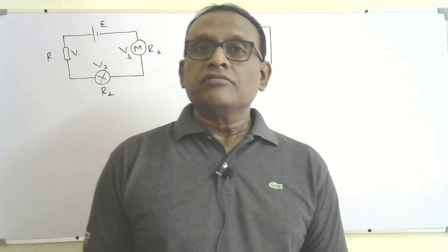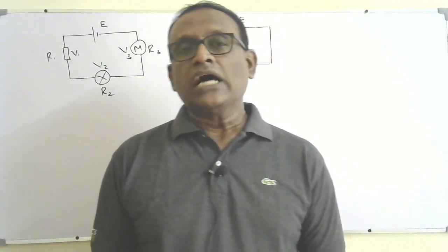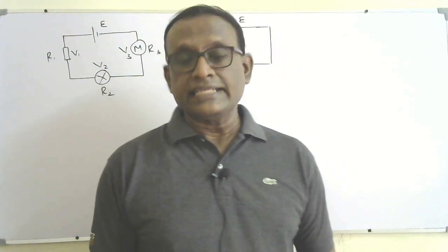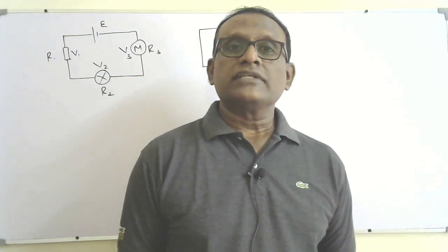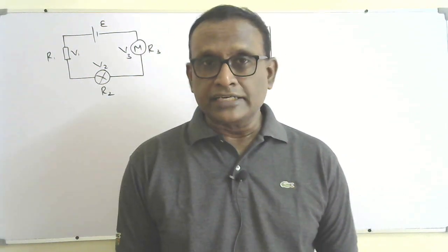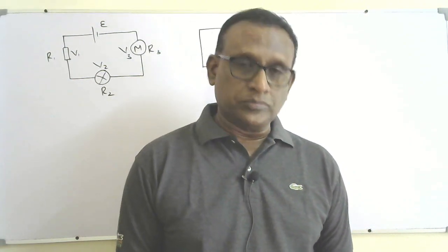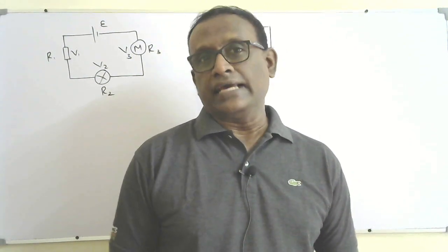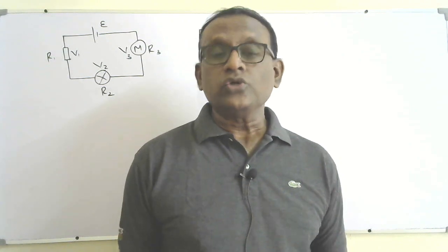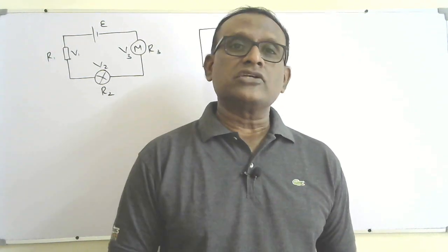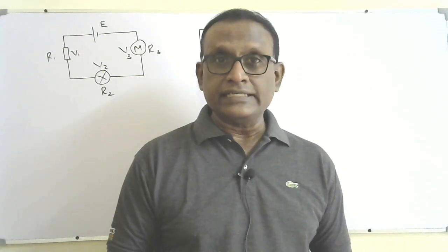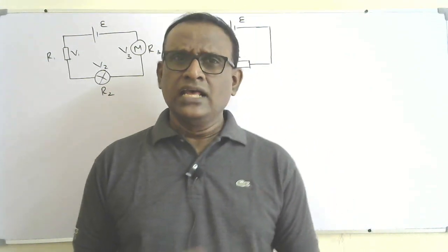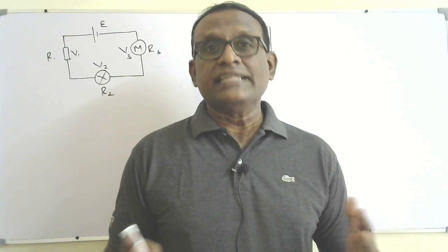During the fourth lesson, we learned how to identify series connection and parallel connection. One of the properties of the series connection is that the same current will flow through all the components. By using that, we can show that the voltage across the components connected in series will be divided at the ratio of their resistance. That is called the potential divider method.